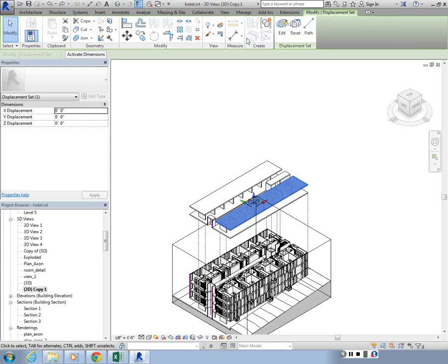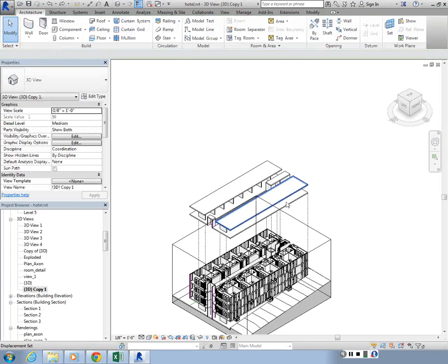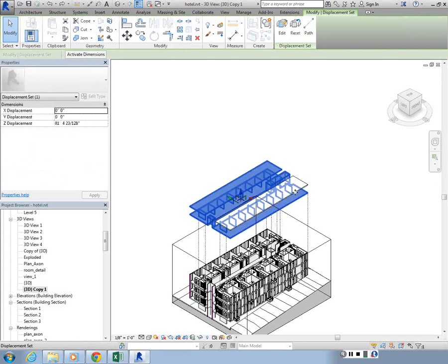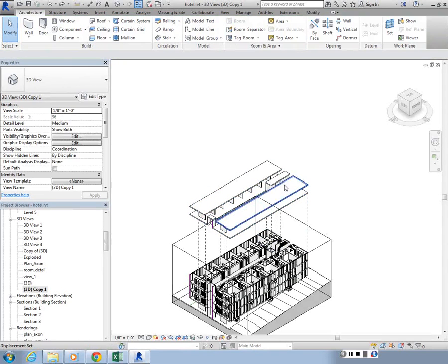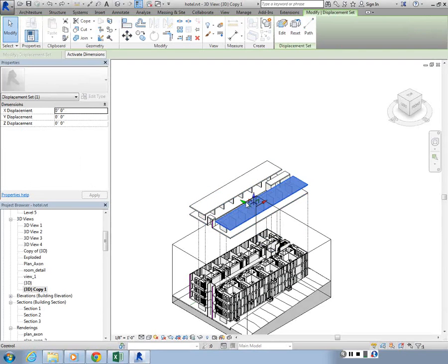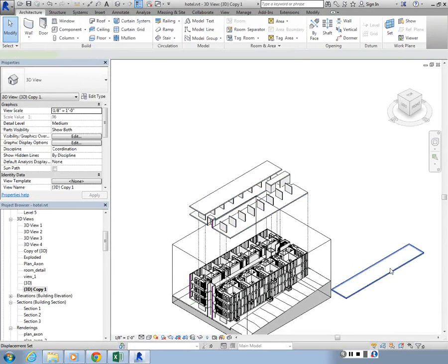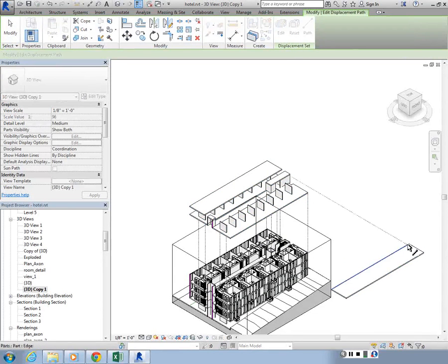So if you come in here, you basically have to choose the individual unit though, because normally they will be grouped under the first displacement group. So you should choose the individual directly, and then you can also add. So it's actually nice. It recognizes its previous group, and then you can draw lines from that.